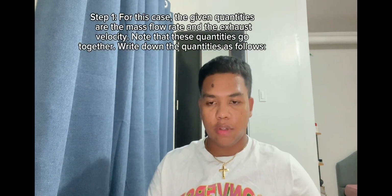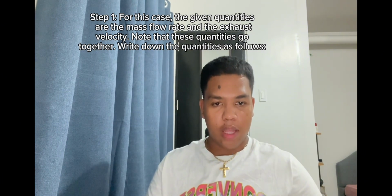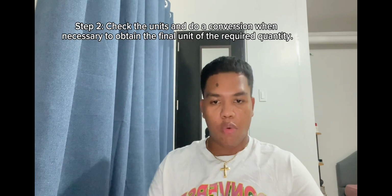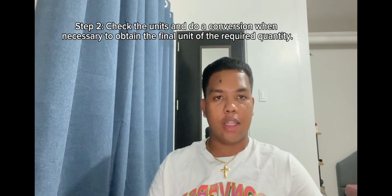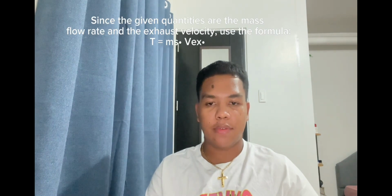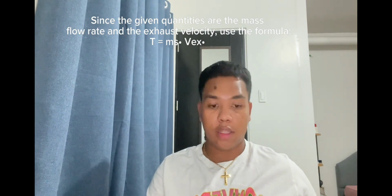Step 1. For this case, the given quantities are the mass flow rate and the exhaust velocity. Note that these quantities go together, so you should write down the quantities as follows. Mass flow rate: 2,200 kilograms per second. Exhaust velocity: 2,900 meters per second. Step 2. Check the units and do conversions when necessary to obtain the final unit of the required quantity. Step 3. Substitute the given values into the formula. The given quantities are the mass flow rate and the exhaust velocity. Use the formula thrust equals mass flow rate times exhaust velocity.